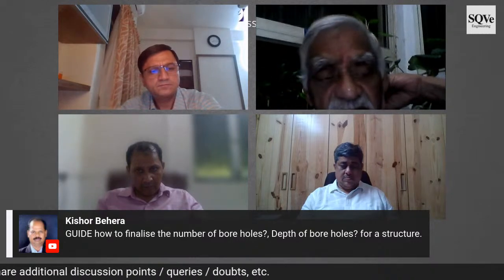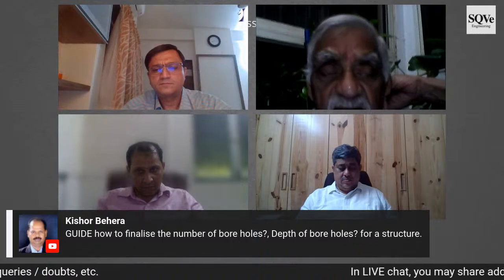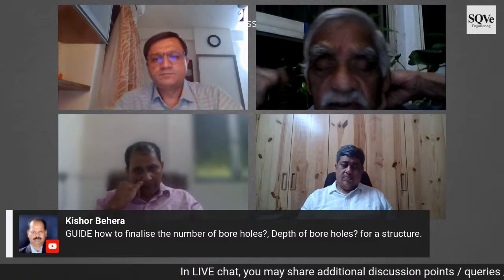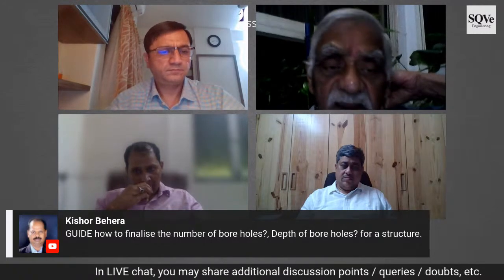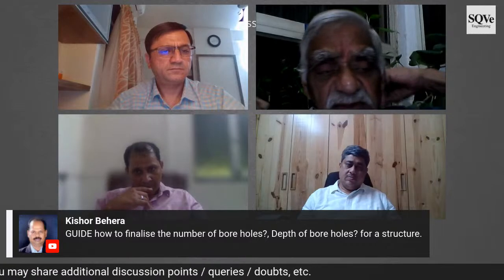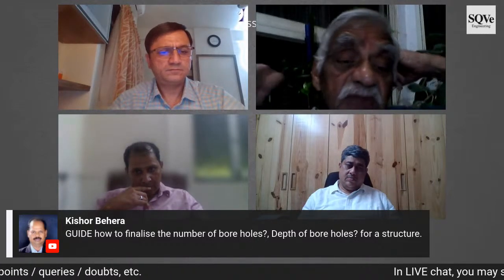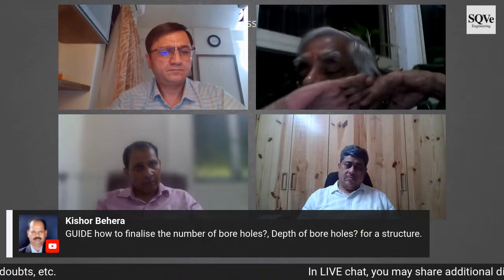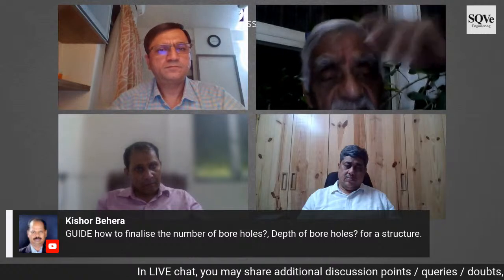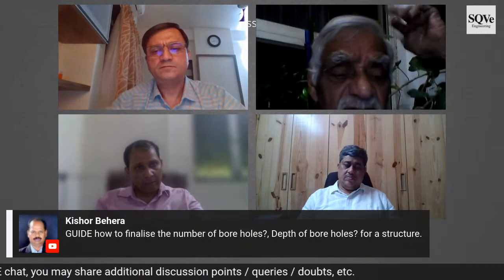You find that data is available and you identify, like when we did Vanakbori Thermal Power Station in Ahmedabad near Godhra. It's a fine, beautiful sand. So we expected 25 ton to 30 ton per square meter, and then we decided the depth of the borehole. And when the investigations were completed, we were not very much off.